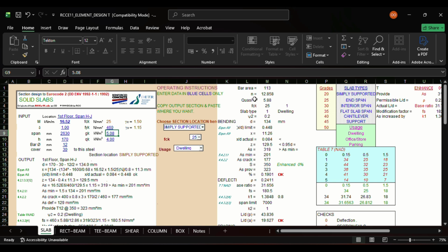So now looking here, this n here is the factored load using these two values. This value is what will be used to calculate this design moment. So we analyze the slab as simply supported and use the formula for design moment. The formula is WL squared over 8. W stands for this value n, L stands for the span of the slab, and then everything divides by 8.